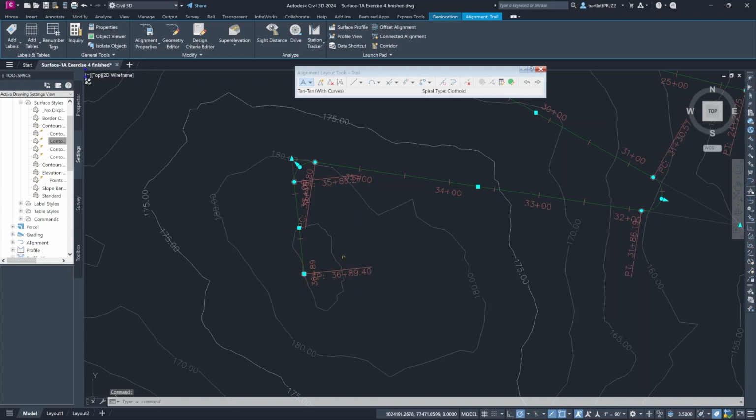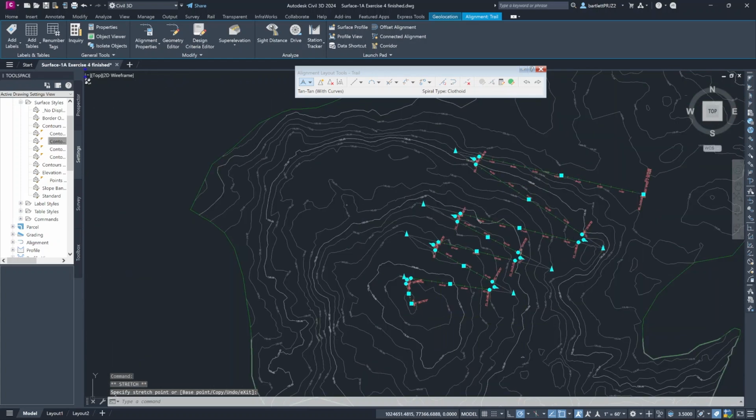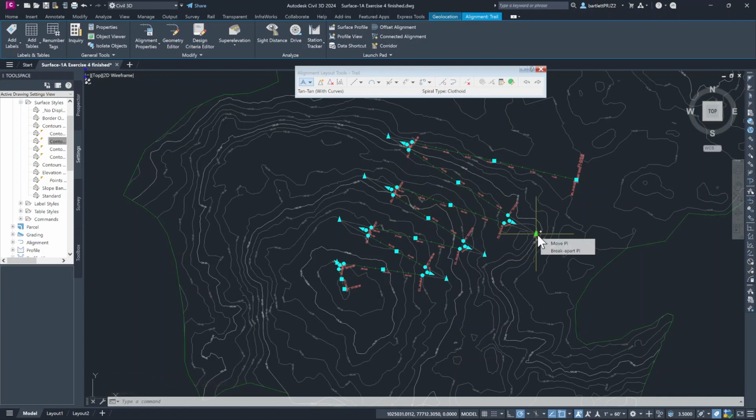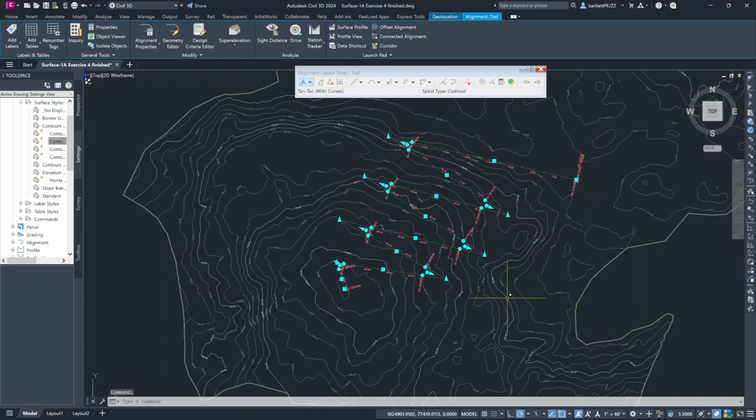I think I want to change this and end this right at the beginning. So remember, you can click on alignment, click on the end, and you can just drag it to where you want it and adjust the alignment any way you want. Maybe we might try adjusting this one down slope a little bit, get this just a little more uniform. I can see some problems here. We've gone across and slightly downhill here, so maybe we'll bring this one back over into that range.